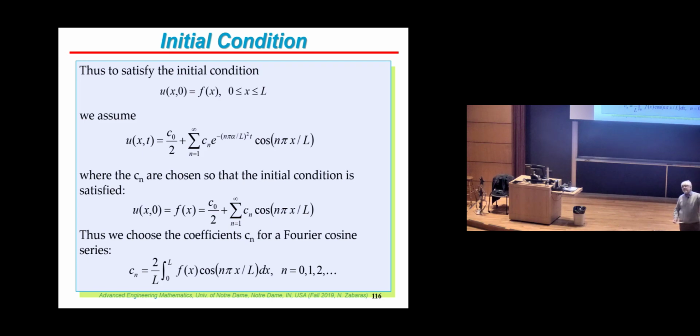Now, there is another boundary condition that's extremely important, right? These are the natural boundary conditions where you specify the flux in a wall that is proportional to the temperature difference. So those boundary conditions involve the flux and the temperature. So what you need to do is exactly the same calculations as we have done, and you will come back with some eigenfunctions and eigenvalues, put them together, and you have a nice series expansion for that case.